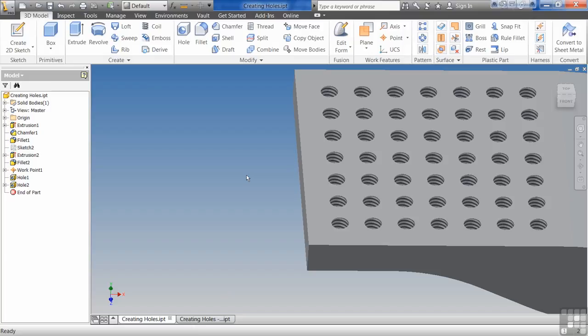Unless you're designing something, if you're designing a screw or some kind of screw shaft or something like that, where you're actually going to be cutting the threads on a CNC and you need to give the CNC information more than just the thread and pitch. This will actually tell it, okay, this is this size thread and pitch when you put it on a drawing. If you're going to pass this over to a CNC machine and they're actually going to go in there and cut these threads and it's got to realize the 3D geometry, then you can draw them in there.